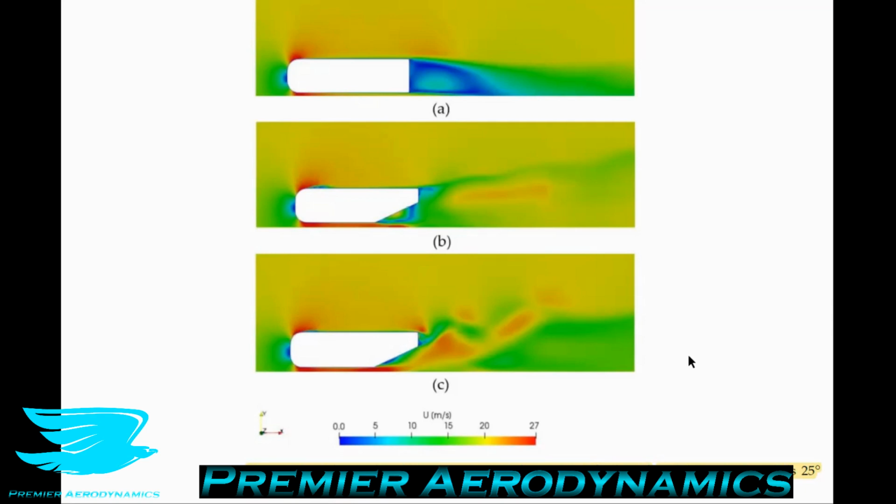So before we even get into the forces, from this point we can already see that there's a greater downforce because the flow is moving up at a steeper angle than any of the other bodies. Even for the body with a 25-degree diffuser without end plates, the flow is moving up at a little bit of an angle, but it's not nearly as severe as this vertical airfoil geometry.